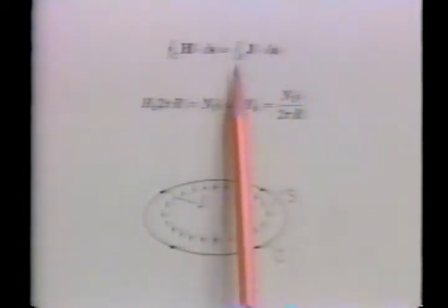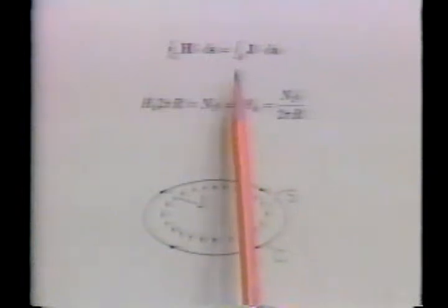Here is the excitation winding. The current is supplied by this variac. The voltage drop across this small resistance in series with the driving winding is used to record the driving current I. This voltage drives the horizontal amplifier of the oscilloscope. Because the H field is proportional to current, the horizontal scope deflection is therefore proportional to the magnetic field intensity H in the core material.